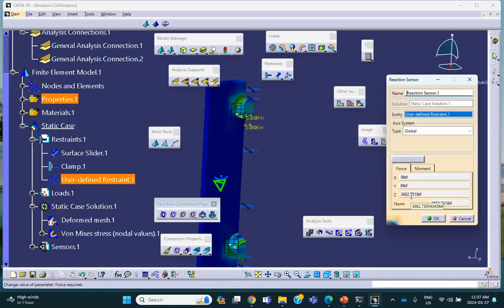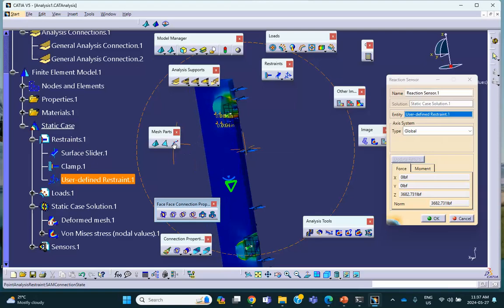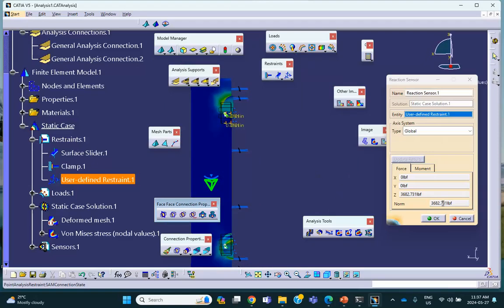I mean, we are not getting exactly half of it, but this requires a more detailed study. You see what happened, okay? You get almost half of what you got before. And there are other reasons that they're different, not quite half, but anyway, without really doing a mesh convergence study, this is all garbage. The first one that I did and this one, you really have to do a mesh sensitivity study in order to get to the bottom of things.